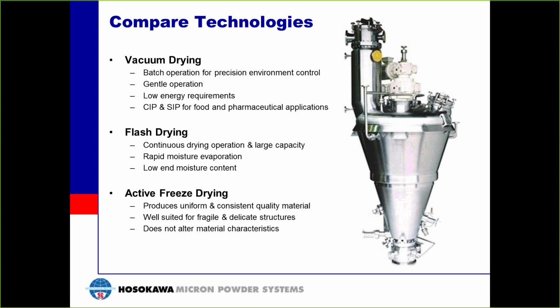All right, so to close out today, we'll just give a quick comparison of technologies. Vacuum drying is a batch operation. It's going to allow you precise environmental control. It's a gentle drying comparatively. It's got low energy requirements. Another thing which I didn't mention, which is nice that it's mentioned here, is you're going to have good cleanability. You can clean in place and sterilize in place for food and pharma applications.